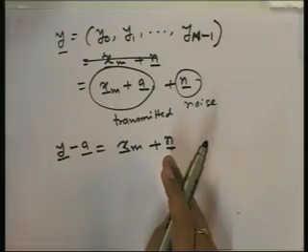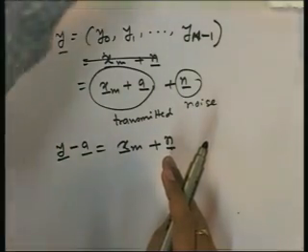Okay. So, we have discussed that the translation keeps a signal set equivalent, meaning in terms of probability of error, the probability of error remains the same even if you translate a signal set. Now, this is not the only transformation which keeps a signal set equivalent. Rotation also keeps a signal set equivalent.